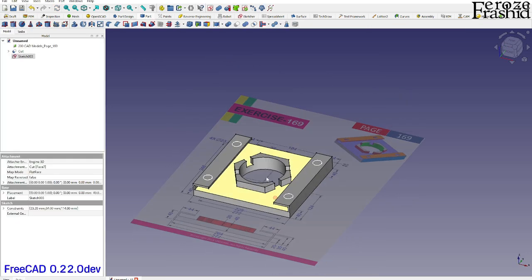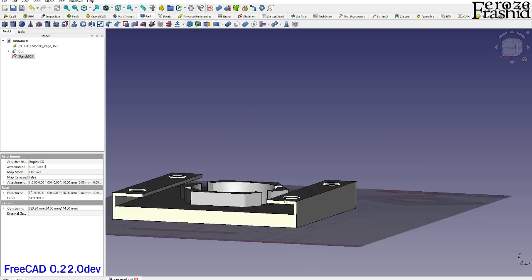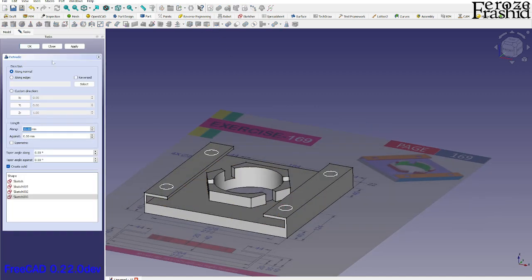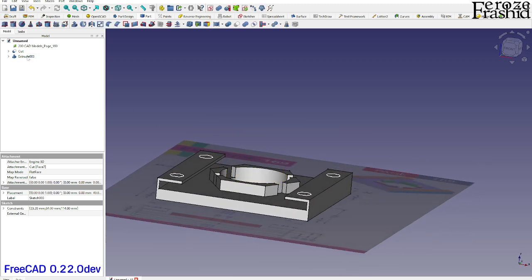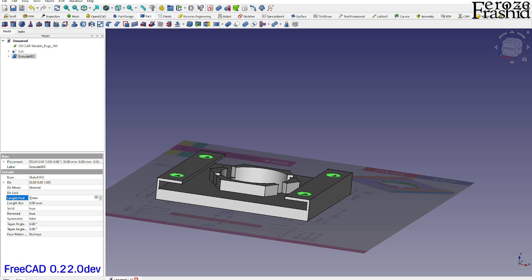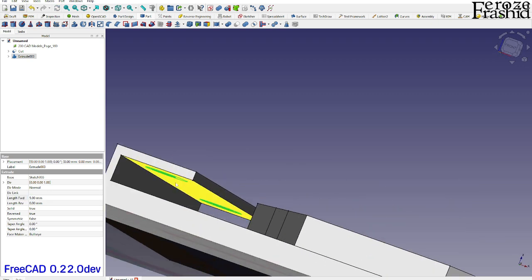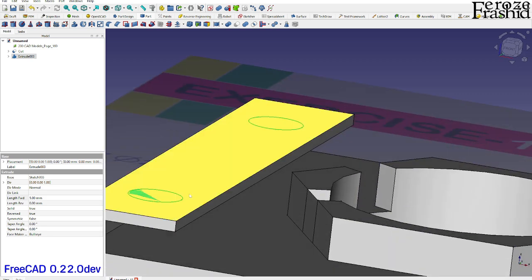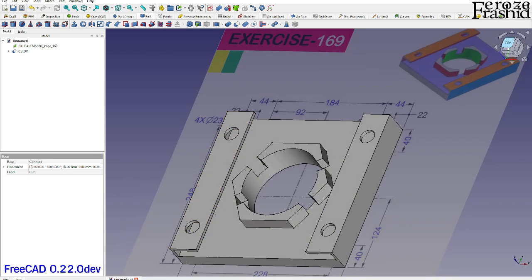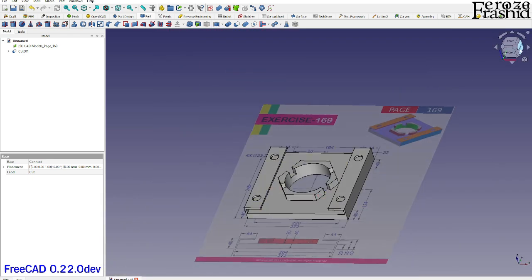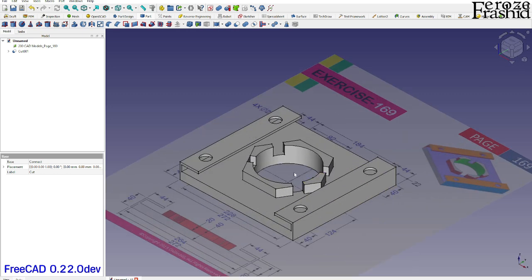So there they are, 4 holes, and I don't want to take it all the way down. It's a little bit. I want to extrude that for say 2 millimeters and reversed. Hit apply, close. I don't see it. Maybe I'll have to extrude that a bit more. Yeah, there. It showed up. So that's 5 millimeter thickness. Now I can go ahead and make another cut from here. And there it is. That's our object built in Part Workbench.